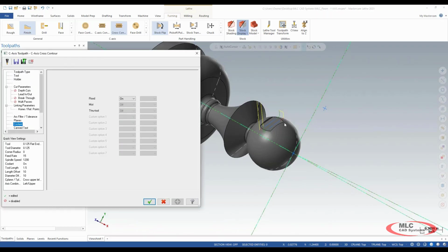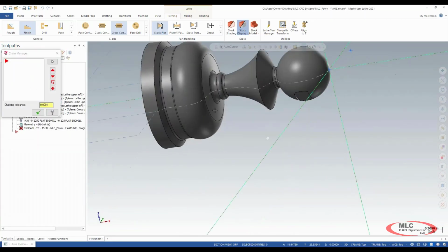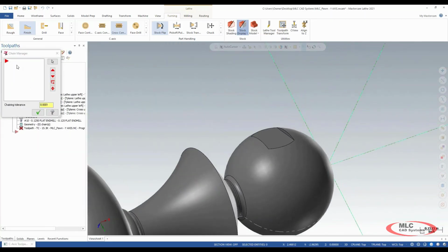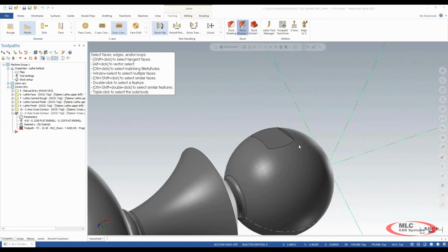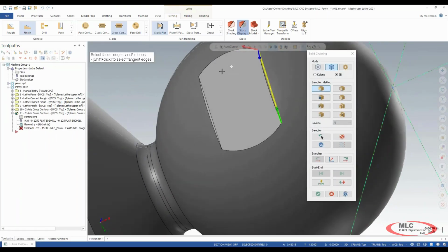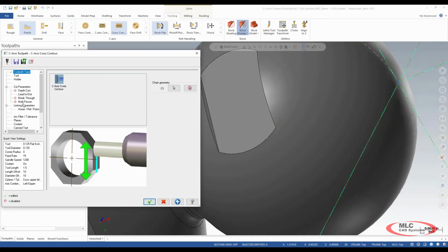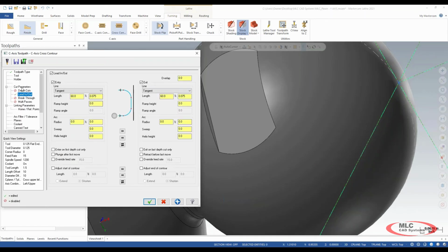So for that front face, I was able to create this milling toolpath. I can also go back to my milling, my toolpath type, based off of a copied operation, and we could even select the other side. Now this operation is going to have all the same parameters that I had before without having to go through everything and put in all this information again.